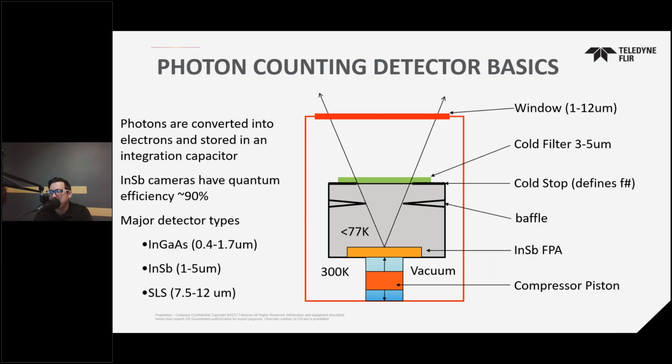So a 3 to 5 micron camera will typically have a lens optimized for a 3 to 5 micron wavelength. And while the AR coatings aren't top hat curves with hardline blocking of wavelengths immediately outside of the specified range, they do affect what wavelengths get to the detector. And depending on the intended range, they could block all the energy. For example, if you put a long wave infrared optimized lens on a mid-wave camera, you'd likely not see anything. And that's because not only is there long wave anti-reflective coating on the material, but the actual material of the lens could be such that it doesn't even transmit in the 3 to 5 micron range.